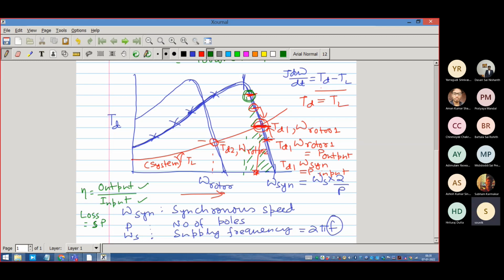So as we operate with higher slip, there will be more loss in the machine. Okay, so this loss in the machine will not be good for us. Therefore efficiency will be reducing. Normally we try to operate at low slip, not too low, but reasonably low. We don't really go beyond 3 to 4 to 5% slip. We don't really go beyond that slip.